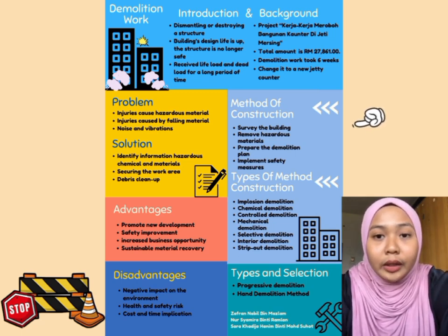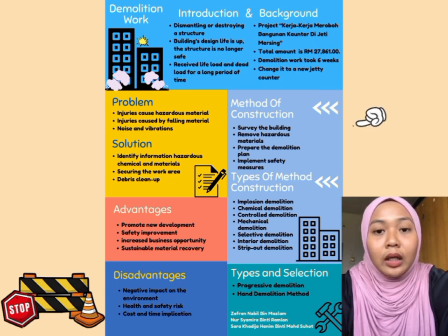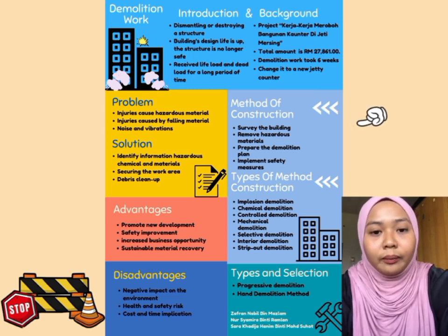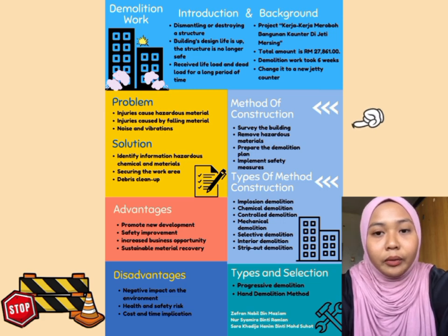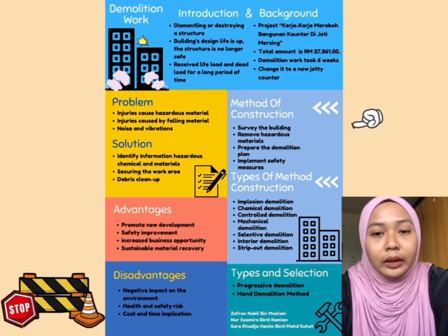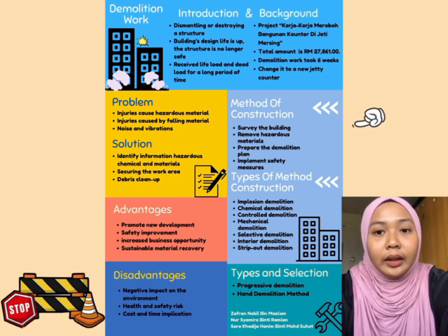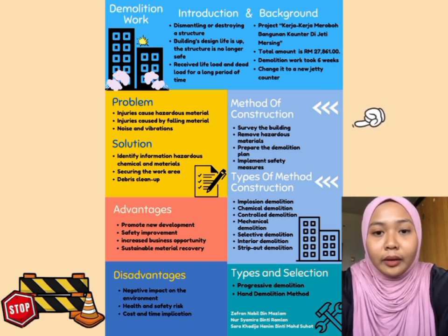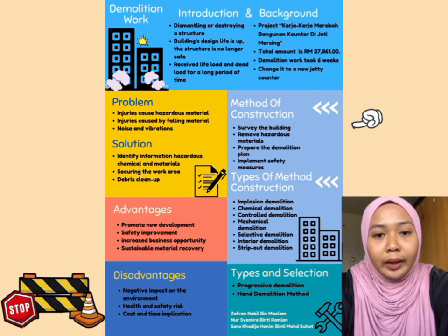The demolition plan should include the specification of which demolition procedure should be used in each section of the building, as well as the sequence in which they should be carried out. We also need to clarify the technique statement for the building demolition, for example, displaying the demolition sequence and the demolition method to be used. Following that, create a waste management plan and a demolition process schedule.